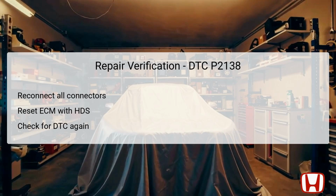Conduct the ECM idle learn procedure as part of recalibrating the system. After resetting, turn the ignition back to the on position. Then press the accelerator pedal fully to check for the appearance of any pending or confirmed DTCs. If DTC P2138 reappears, inspect connections and terminals at the APP sensor and ECM for loose connections. If all tests are clear, the troubleshooting is deemed complete. If any other trouble codes arise, further diagnostic procedures related to those codes should be initiated.